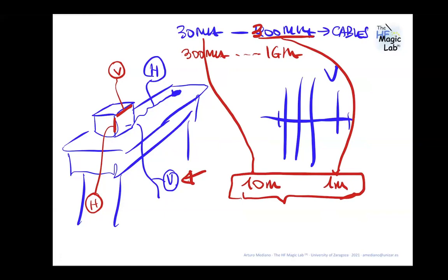Is it essential to have the antenna factor considered during measurements with the oscilloscope? No. It's good information, but usually when we are debugging, we look for qualitative differences. We are not specifically interested in some value of voltage or current.